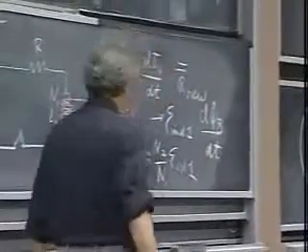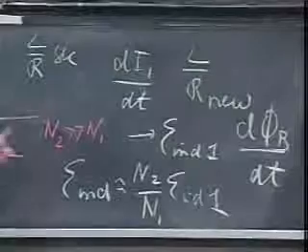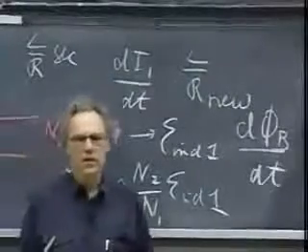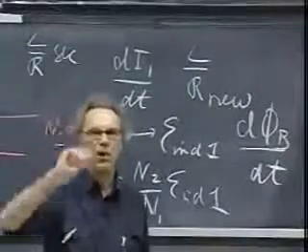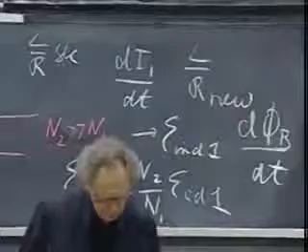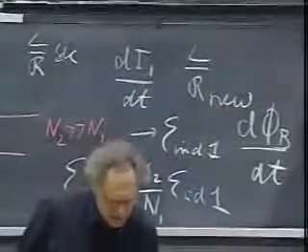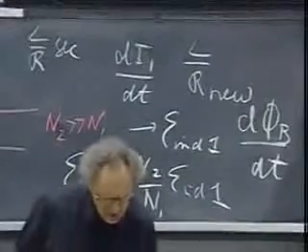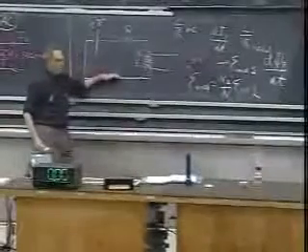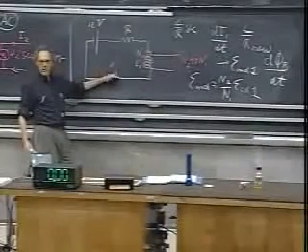In your cars, that is not necessary. It is enough in your cars that you get here something like 10 kilovolts. And that will comfortably give you a spark over your spark plug. And so what is happening with your car, without you realizing it, there is a circuit that closes and opens and closes and opens and closes and opens.